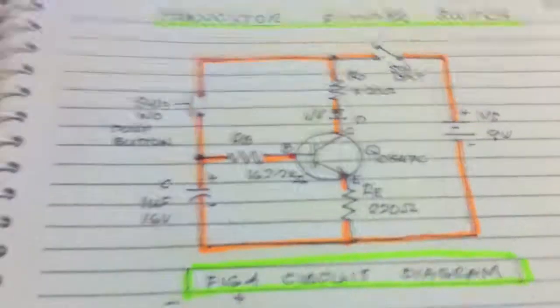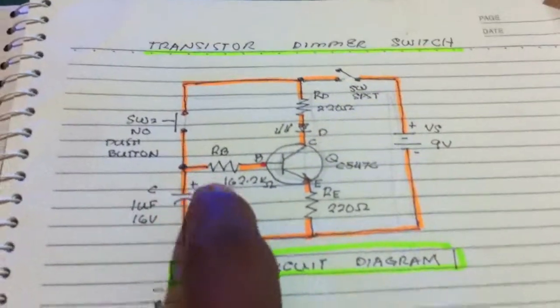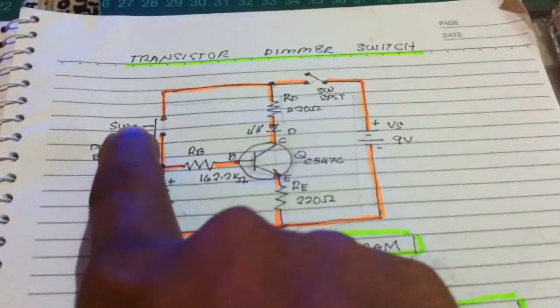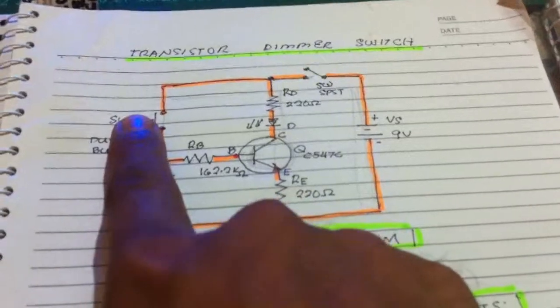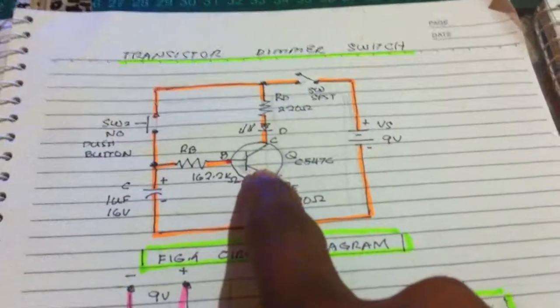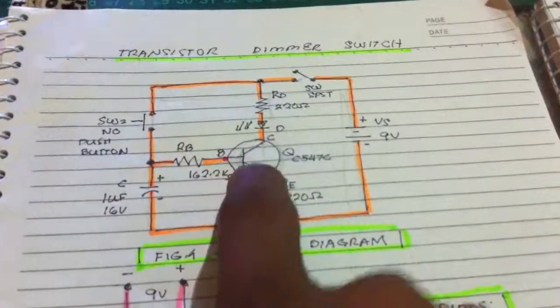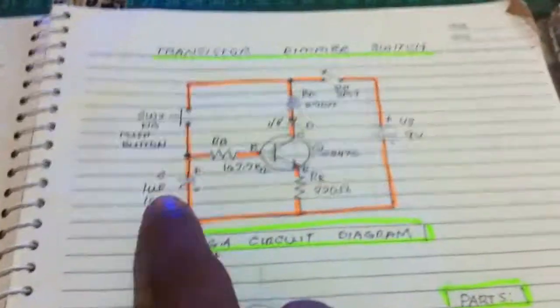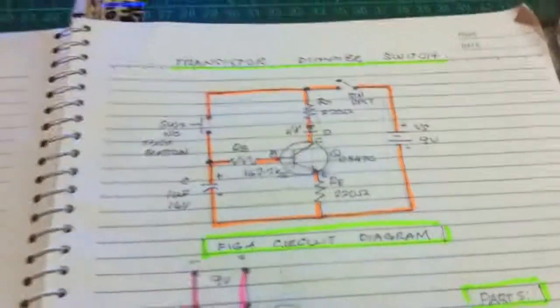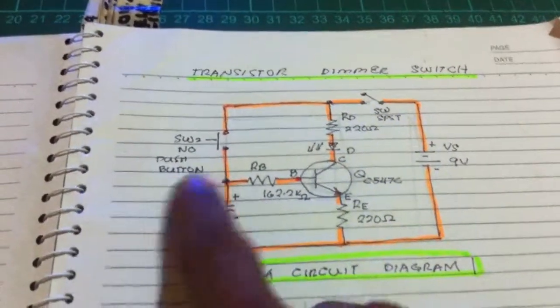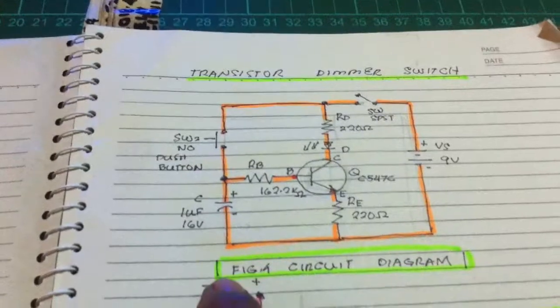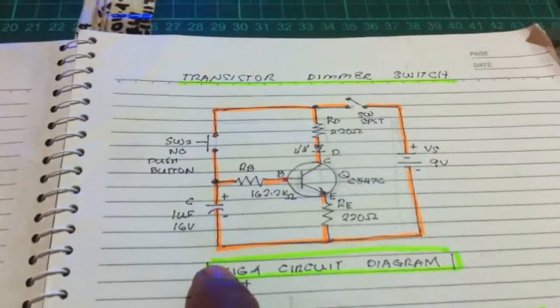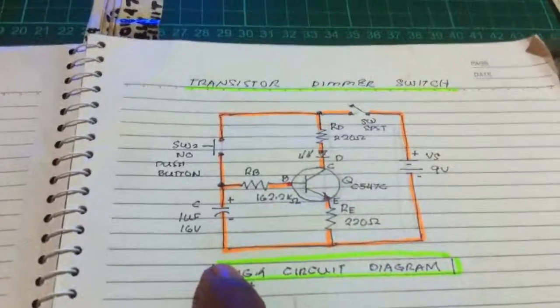We're going to put a resistor here, a pull down resistor for the switch. I need a pull down resistor for the switch. This resistor is for the transistor biasing, a resistor for the base current, and a resistor for the LED. And if we put a resistor here, maybe the discharging effect will become so fast. It will become much faster than this one.